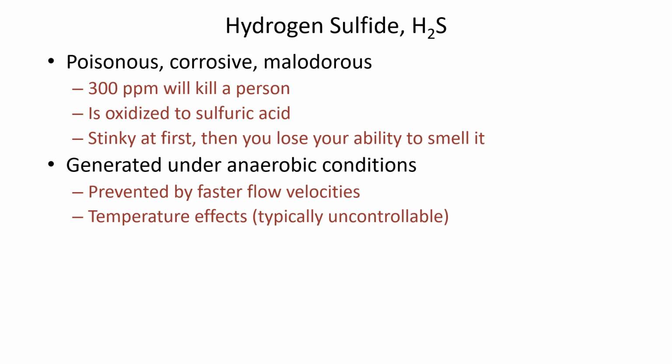And it's also corrosive because hydrogen sulfide is oxidized to sulfuric acid. And so it causes pitting of concrete pipes. It can cause premature rusting and oxidation of metal in wastewater treatment plants if hydrogen sulfide is formed.